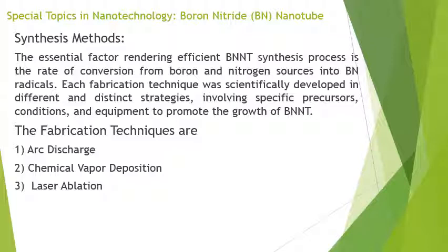The multi-walled boron nitride nanotubes were synthesized by laser heating cubic and hexagonal BN targets up to 5000 Kelvin in a diamond anvil cell under extremely high pressure of nitrogen gas.